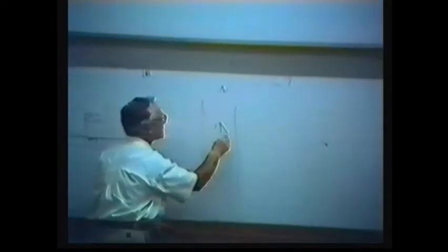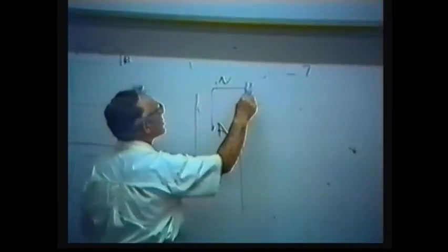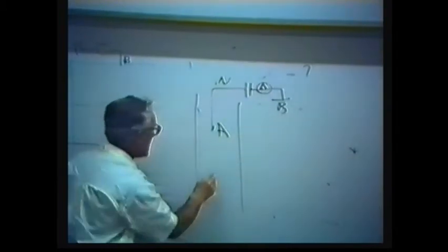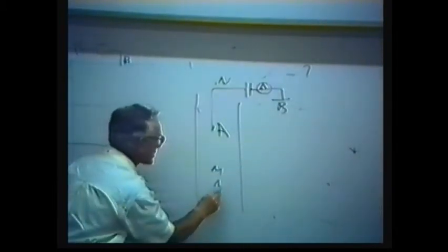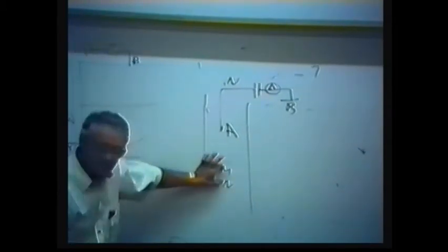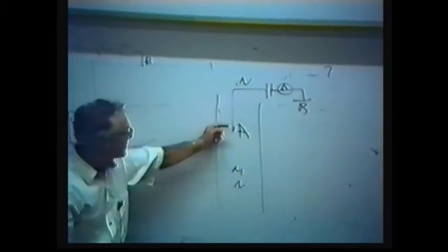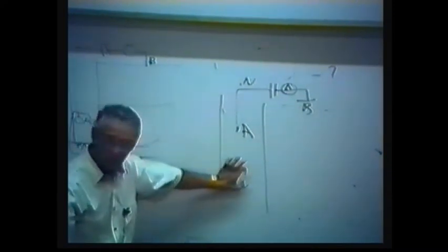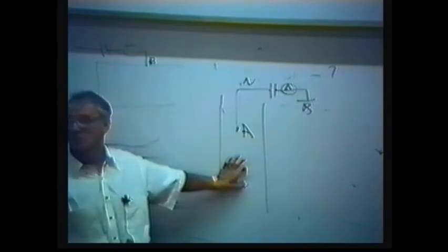You have a current electrode, again surface, again ampere meter, again electrode B, and now two electrodes in the borehole. Distance between MN is usually smaller than between A and M. Let us say 1.5 meter, MN 20 centimeters.